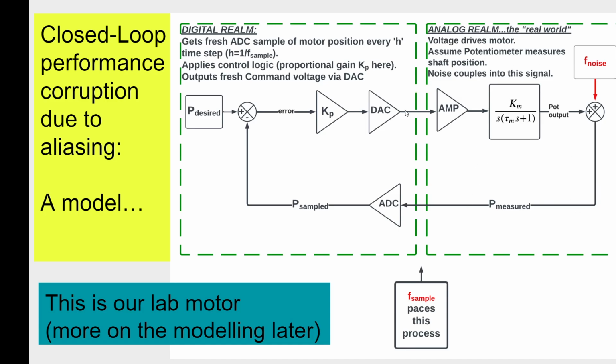So we've sampled too low for a frequency component that's on the input line to our analog to digital converter, and we have folded that frequency, in this example, down to 1 hertz, where we are indeed sensitive.